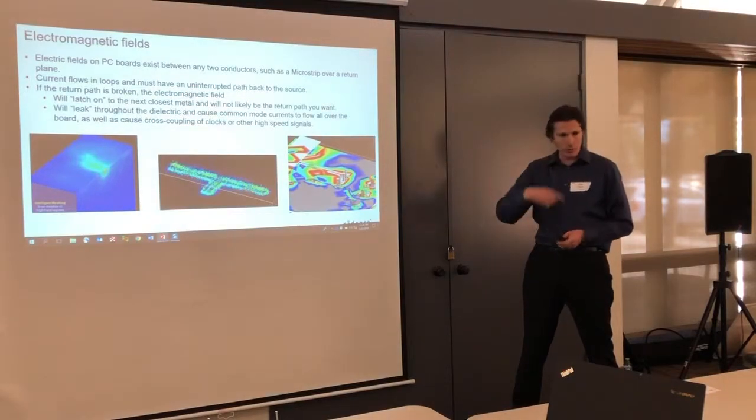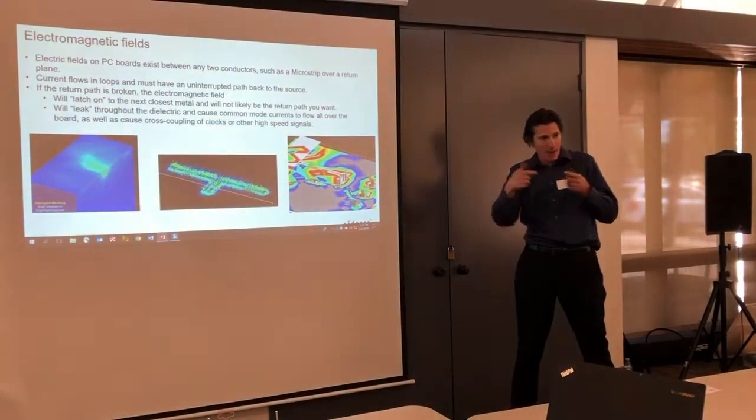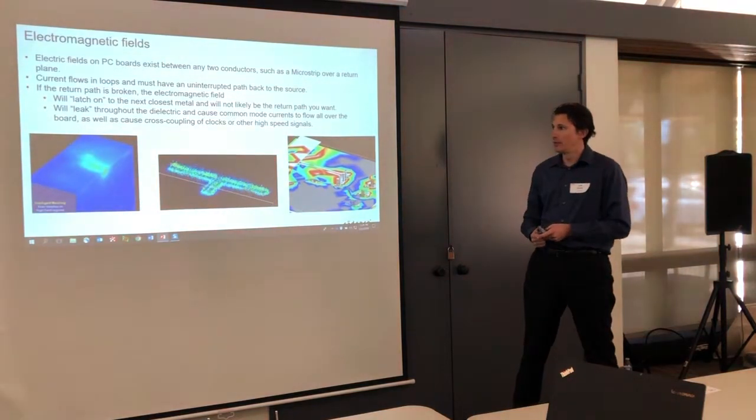And so current always wants to flow in a loop. It's going to find a way back. Your job as a designer is to try to keep that way back as close to the conductor as possible. Okay.